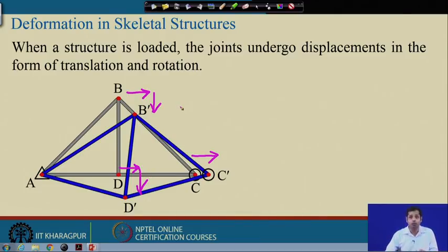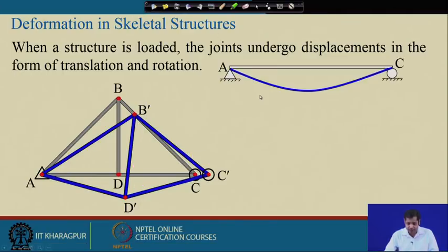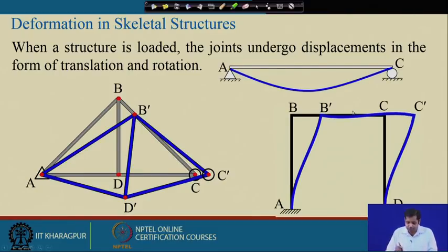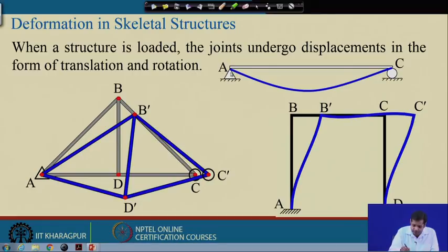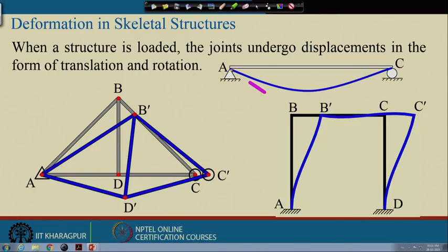Okay. In a truss you do not have rotation, because only translation degrees of freedom exist in a truss member. Now, the kinematic indeterminacy, for instance, for a beam: these are the rotations. This is the rotation for a beam, and for a truss also, for a frame also, this point goes here and this point rotates like this, depending on the support condition and the constraint you have, right.